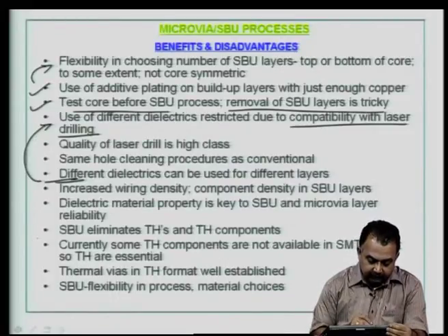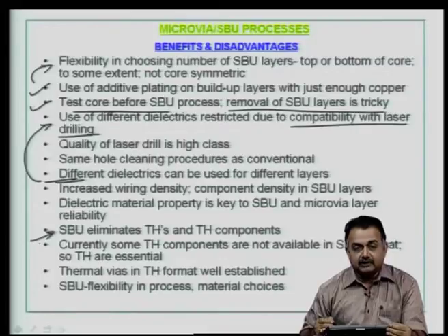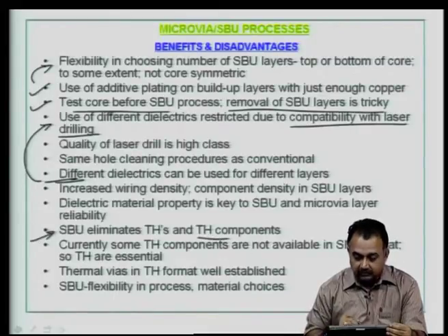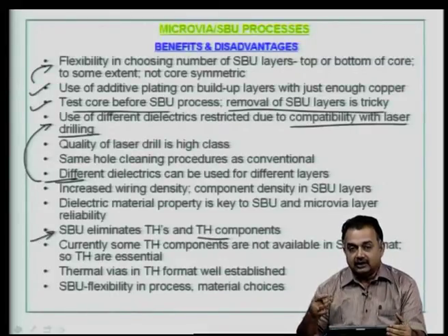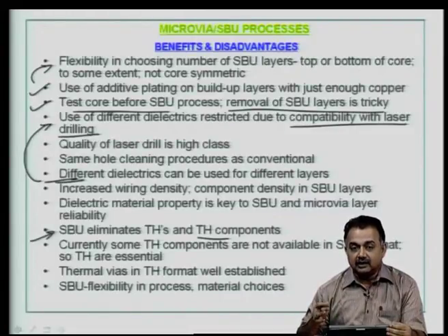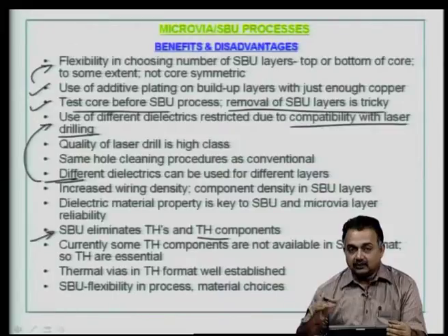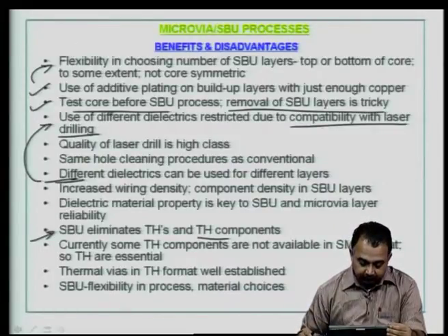So, finally, SBU obviously eliminates the through holes and the through hole components. So, you can advance or migrate into non through hole components, that is surface mount devices as well as bare chip, BGAs, CSPs and so on.